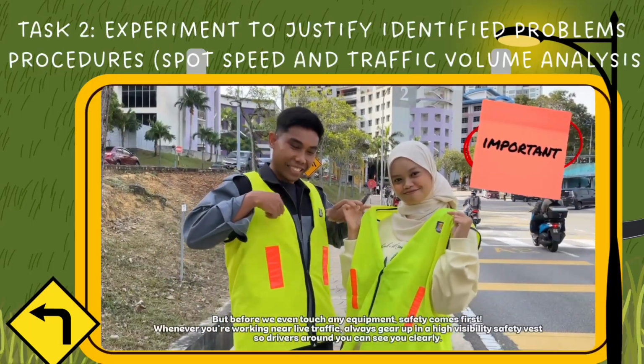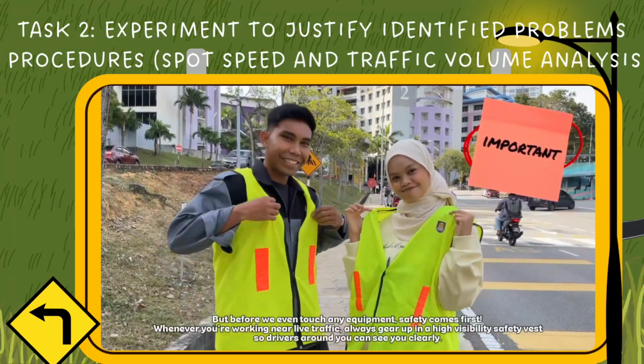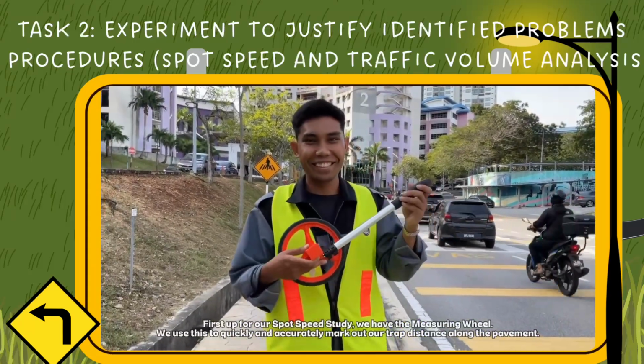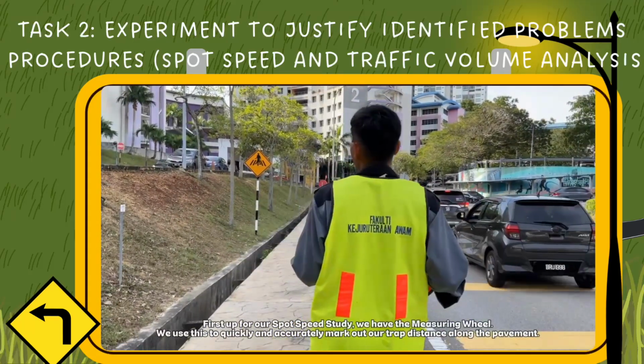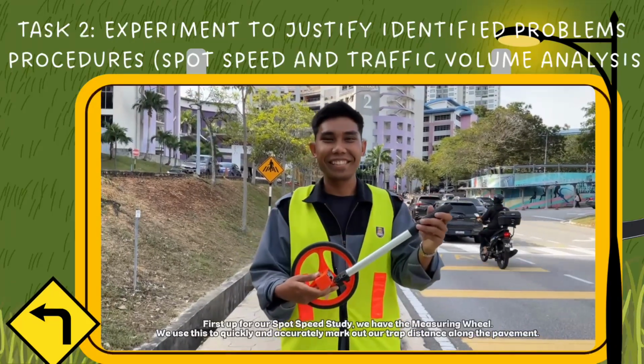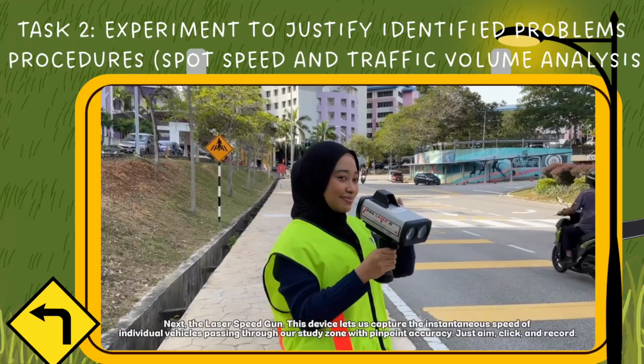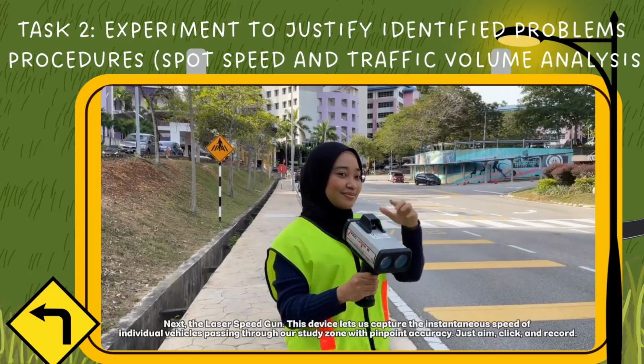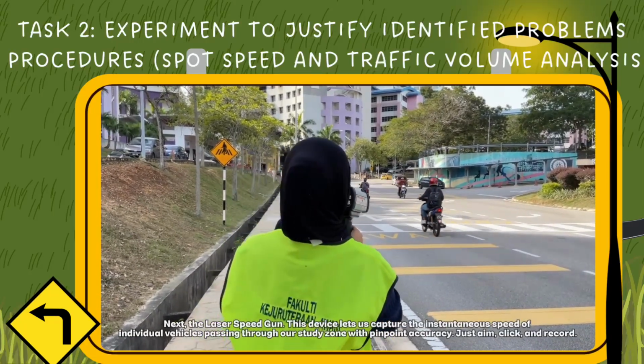Whenever you are working in live traffic, always gear up in a high-visibility safety vest, so drivers around you can see you clearly. First up, for our spot speed study, we have the measuring wheel. We use this to quickly and accurately mark out our track distance along the pavement. Next, the laser speed gun. This device lets us capture the instantaneous speed of individual vehicles passing through our study zone with pinpoint accuracy. Just aim, click and record.